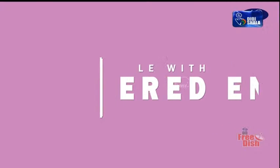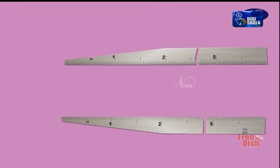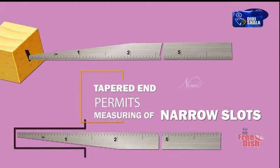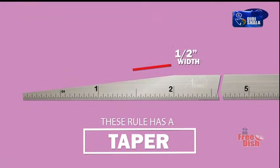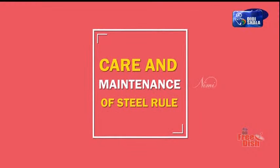The last and final one: steel rule with a tapered end. This rule is a favorite with all mechanics since its tapered end permits measuring the inside size of small holes, narrow slots, grooves and recesses, etc. This rule has a taper from 1/2 inch width at the 2 inch graduation to 1/8 inch width at the end. Now, we will see the care and maintenance.